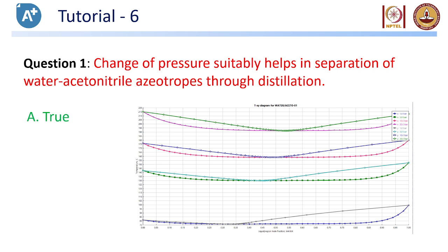Accordingly, it will change. Depending on the azeotrope temperature and the composition, you need to design the sequencing. And RCMs, residual curve maps, will be useful in designing this sequencing, because you will be able to see at what composition and temperatures you are getting the azeotrope. Dividing the RCM with bifurcation things will help you out in which region of the RCM you have to put columns and all. So that is a different course itself about sequencing the distillation columns.